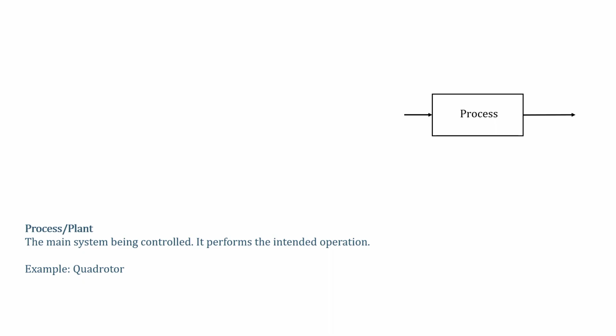The example here can be a quadrotor. Remember the quadrotor that we had discussed? The transfer function came out to be 1 by s square, remember? Suppose that quadrotor can move only in the z direction. There is no x and y movement, only in the z direction it can move, and we found out that the transfer function of the system is 1 by s square.